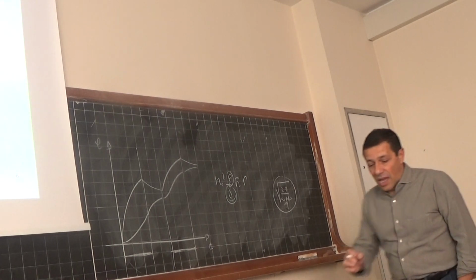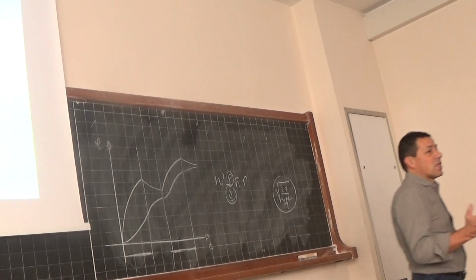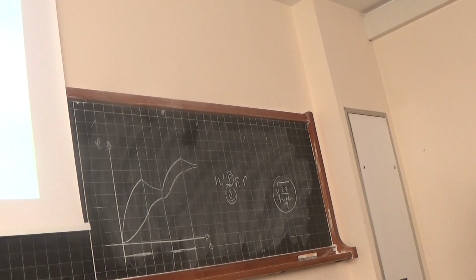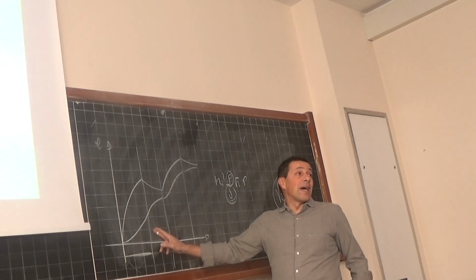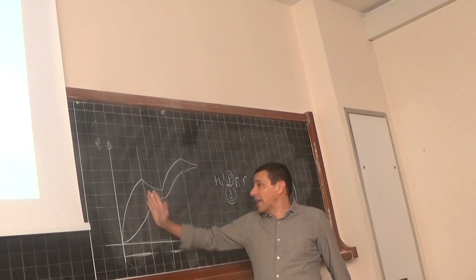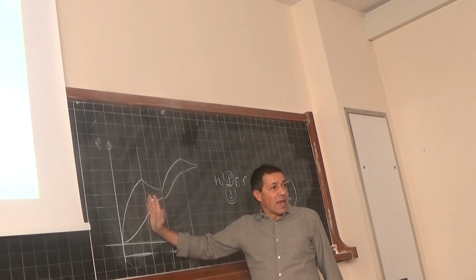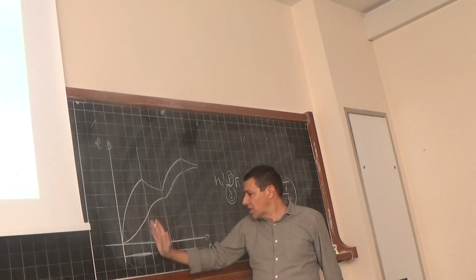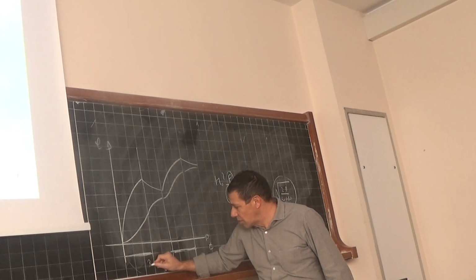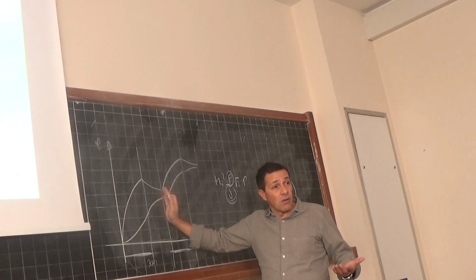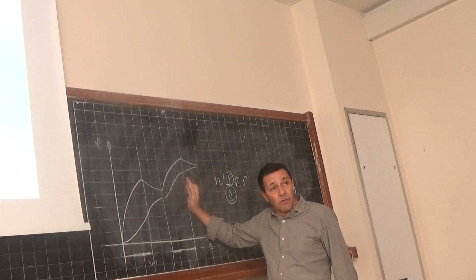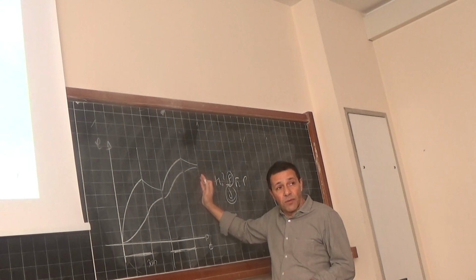In this case, for example, we use a stationary machine. We put the billet inside the inductor and we wait. So it means that in this case we are speaking about time. I switch on my inductor for a certain time, for example 30 seconds, then I switch off the inductor for 10 seconds, then I switch on again for 30 seconds, and then I switch off.